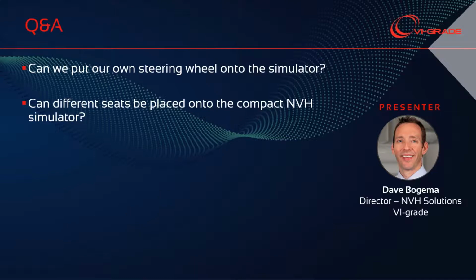Another aspect of that is the way we've designed this seat. And again, something we've learned from developing these things in the past. If you try to shake the entire seat structure and the person and everything, it's a lot of mass, and you run out of force very quickly out of your shakers. So what we're doing is we're moving the smallest amount of mass possible. We're actually shaking the person himself and not the overall seat.